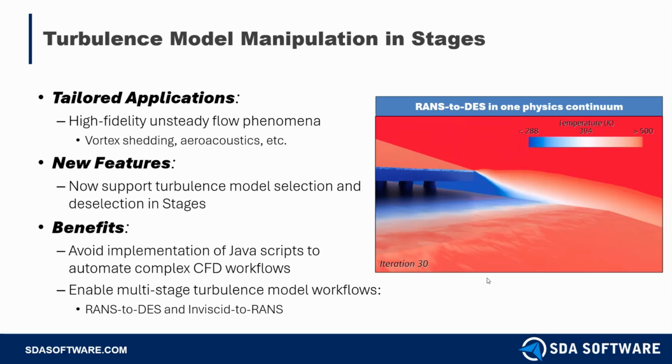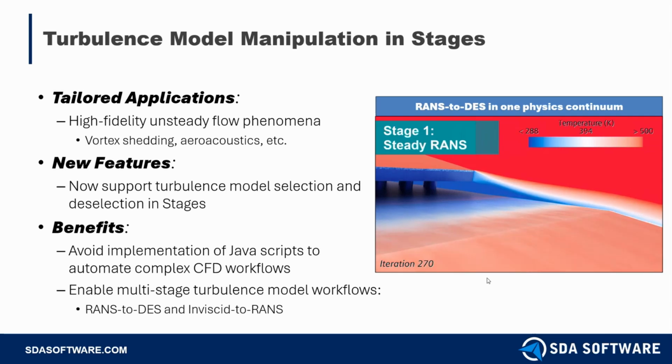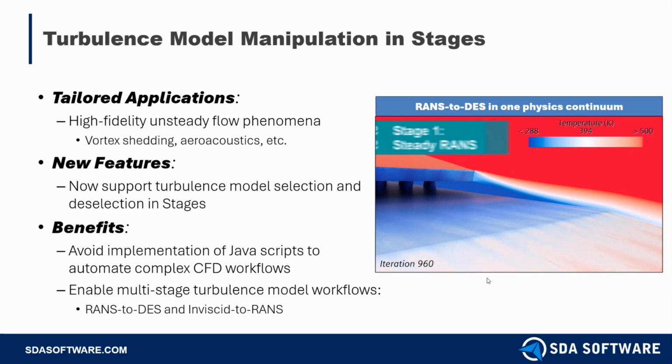This new feature is especially useful for multi-stage turbulence model workflows like RANS to DES, Inviscid to RANS, or even DES to LES, depending on your fidelity.